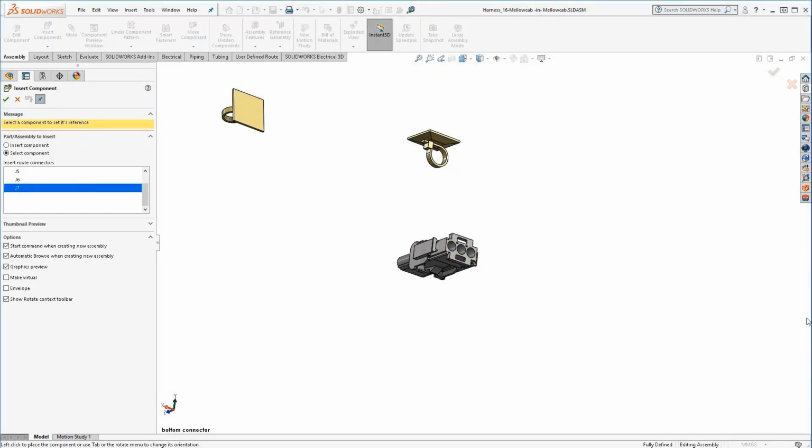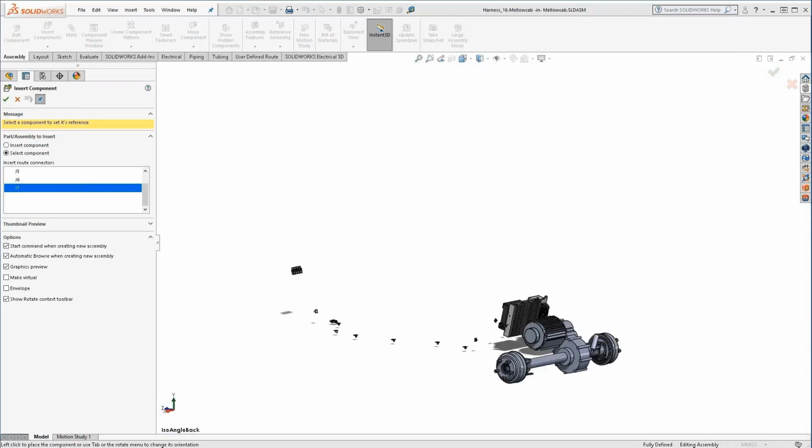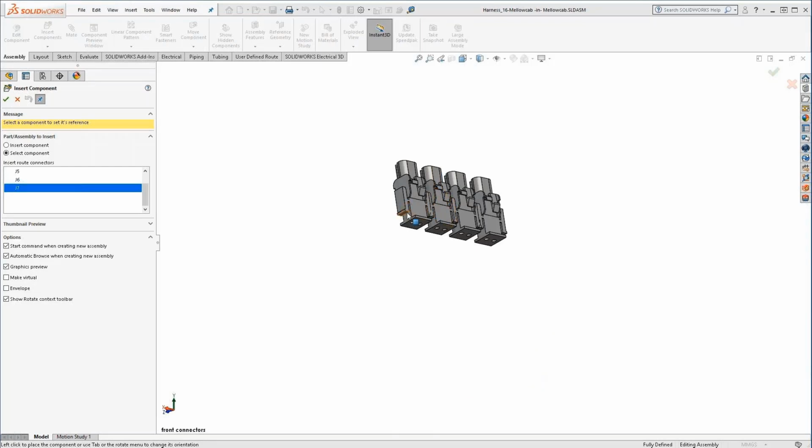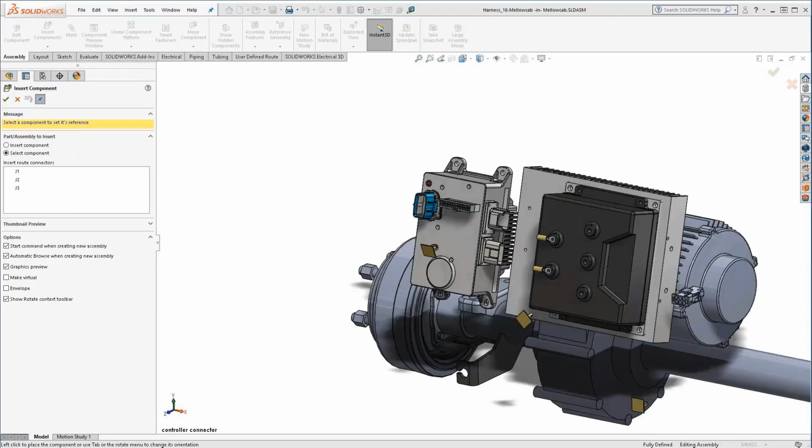Okay, very easy again. So you can see, once you load the Excel, you are not only taking the connector name and using that in SOLIDWORKS. Once we use the connector and we link that connector with a part here in the assembly, we are also bringing all the information about the connections. We also bring in the wire type, because we know the two ends of the wire. We are bringing the wire type and color, as you saw before, and everything.